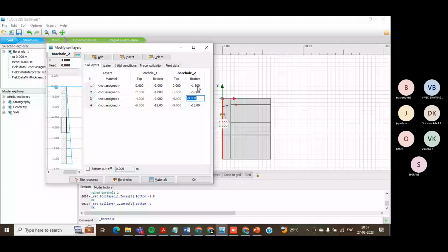Okay, now see this. Now you are able to enter the borehole information, and you are able to assign the number of soil layers as per your wish. So do you have any questions? This is the very first basic step that we need to go for with the soils. When we are going for the soils, you have to add these particular borehole information.